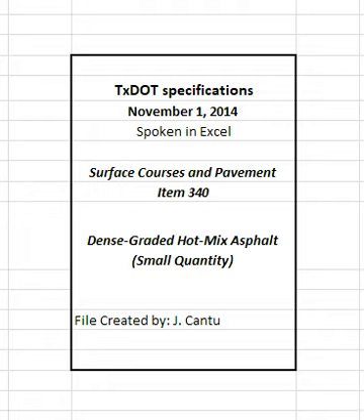Schedule and participate in a pre-paving meeting with the engineer on or before the first day of paving unless otherwise directed. 4.1 Certification. Personnel certified by the department-approved hot mix asphalt certification program must conduct all mixture designs, sampling, and testing in accordance with Table 6. Supply the engineer with a list of certified personnel and copies of their current certificates before beginning production and when personnel changes are made. Provide a mixture design developed and signed by a Level 2 certified specialist.